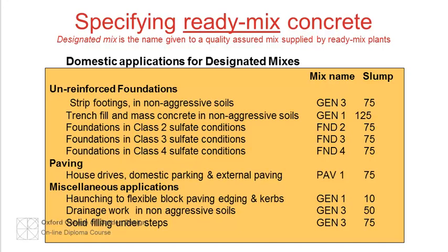Apart from quoting the designated mix reference given in the table, the contractor need only state workability, reinforcement if any, and any special design requirements affecting the way the concrete is to be placed and any method of finishing the surface. The ready-mix supplier then takes full responsibility for the materials and quantities used to meet the requirements, including durability. 20 mm aggregate will be used unless otherwise specified.